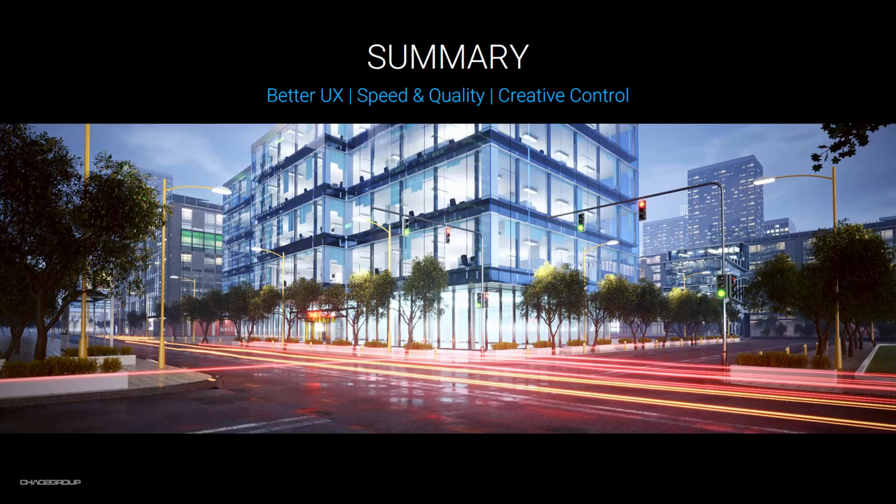We have also made it easy for you to switch between the two different rendering engines that come with V-Ray. They're completely different. One is CPU based, one is GPU based. And it's very easy when you're on the GPU to switch between devices, and you can render on the CPU only or on the GPU, or you can render on both of them at the same time, which I talked about, and it can be very advantageous.